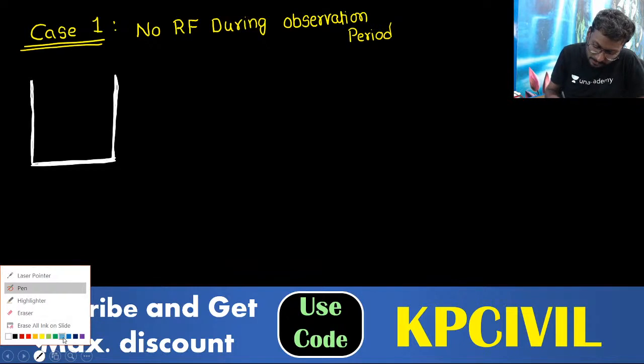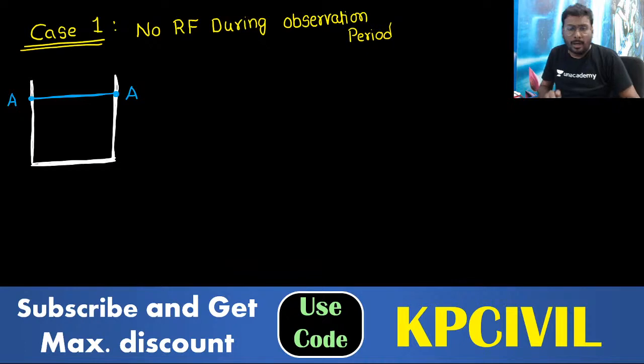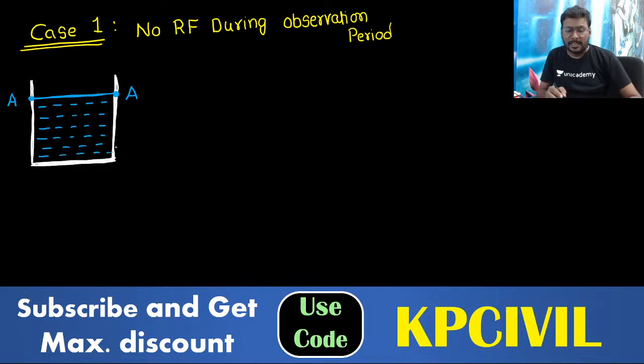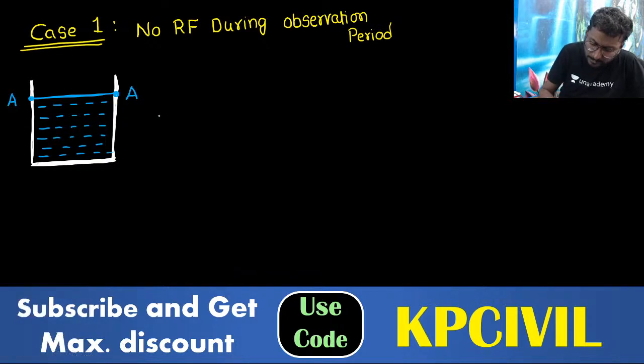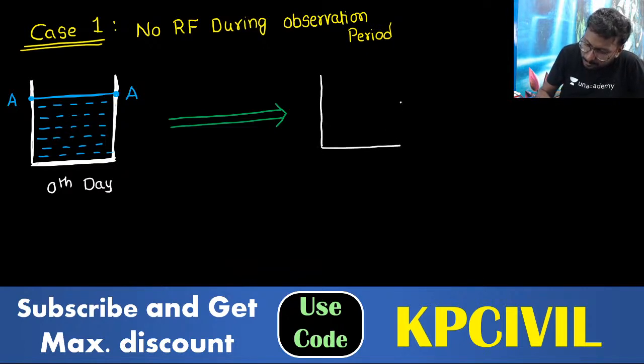So on day 0, you have filled the water up to the level. Remember, up to level A, we call it the stipulated level. Volume of water is filled up to level A on day 0, the starting day of experiment. And for example, your observation period is T number of days. This is the 0th day. Observation is carried out, T days completed.